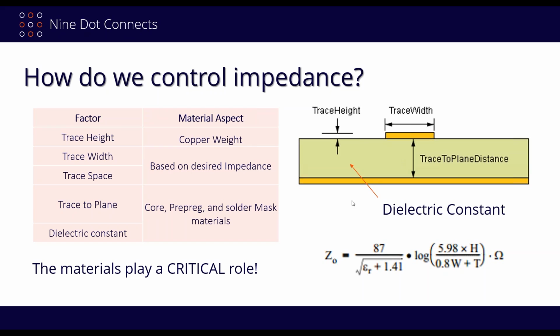And that's why this is so important for us to address immediately and not at the end of the process. The problem that most of us have, especially if we come from what I'll call the old school, and we're using FR4, and we'll talk about FR4 in a couple of minutes. The point I want to make there is that in the past, since we're using FR4 and we knew it so well and we weren't worried about high-speed issues or impedances, if we were starting off with a 2-layer board, we're trying to make it fit, and if it didn't work, okay, throw on another 2 layers.